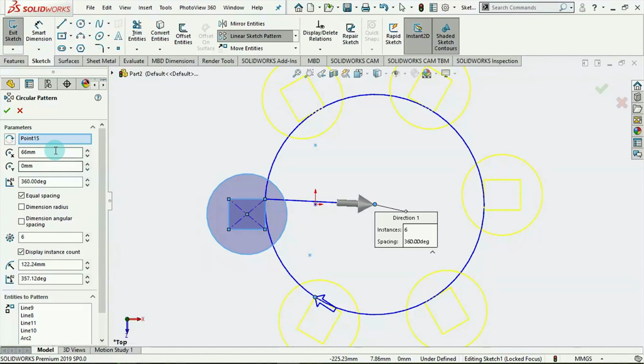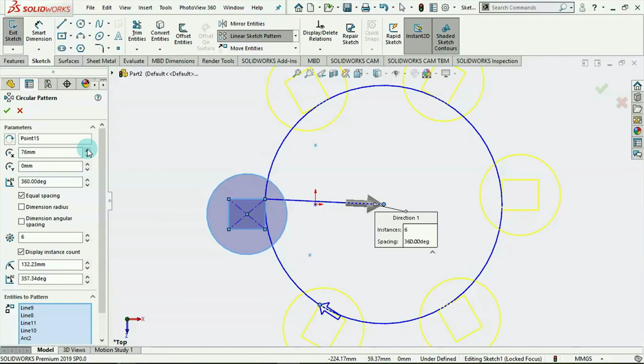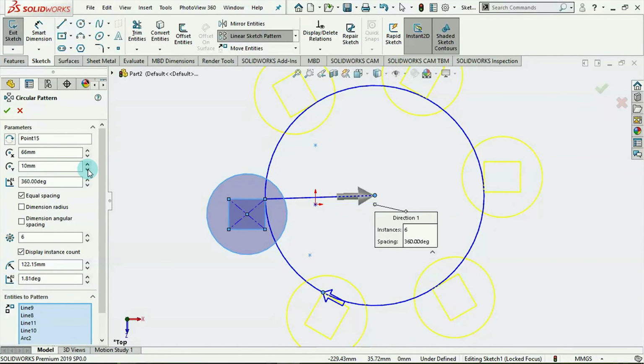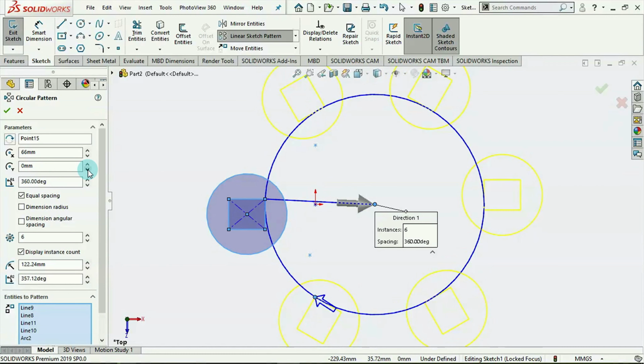At this point, you notice how we have dimensions here. I would prefer you do not touch this, because this is what is used to change the location of the center. So if I increase this, you notice that that goes forward. I bring this back, it comes backward. I increase this, it takes it up. Take this, takes it down. So it's advisable that rather than using this, you already dimension your points. And just like I said before, you find all of these in the tutorials covering points.